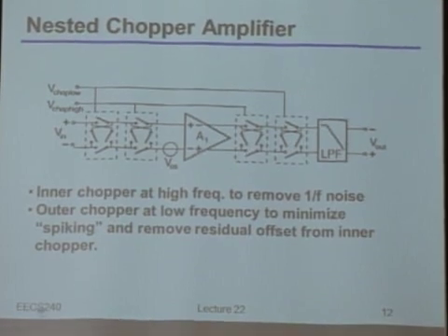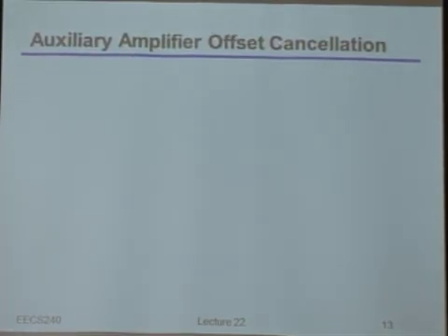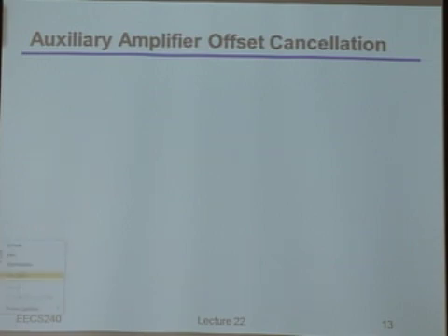Okay, good. So if we start thinking about the second general technique, the whole idea is just to find some DC signal that will cancel the offset. I wanted to remind you of one of the techniques that I believe you talked about in the multi-stage amplifier lecture, of how you would come up with that DC signal to cancel the offset in the first place. So let's say you had some input, and this is where we're going to do the subtraction. And then we take our amplifier. And by the way, somebody asked earlier, I'm drawing everything as real op amps here. The idea is very similar with OTAs, and would basically work the same way.